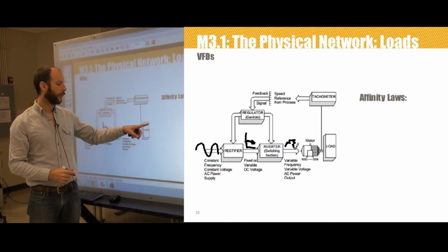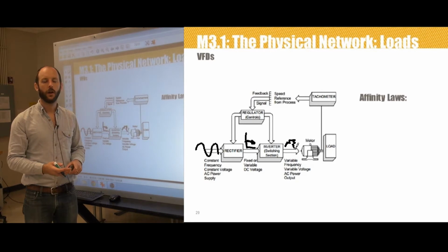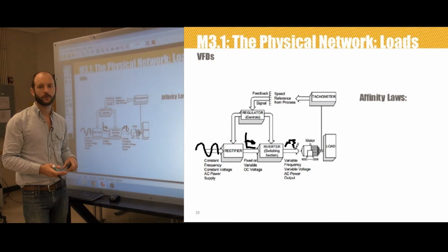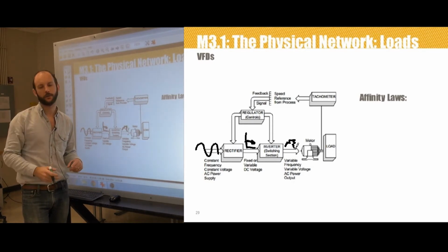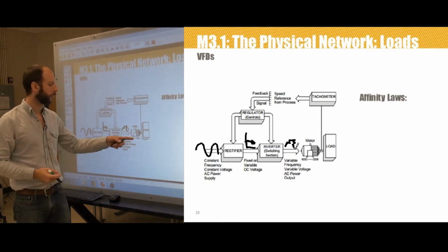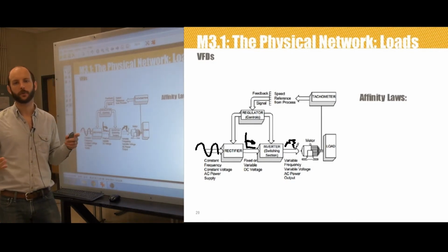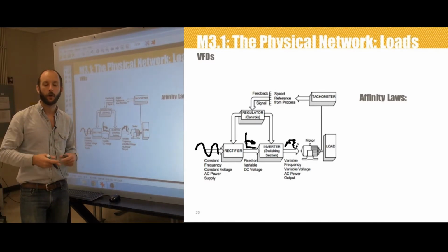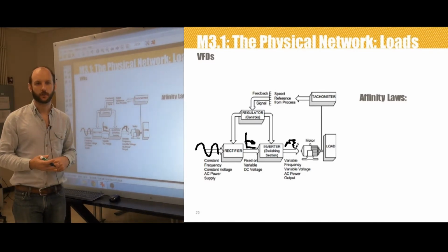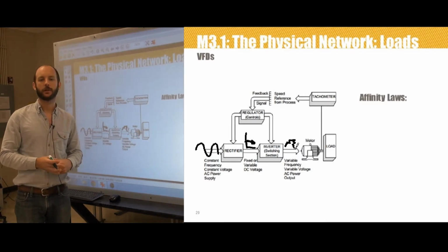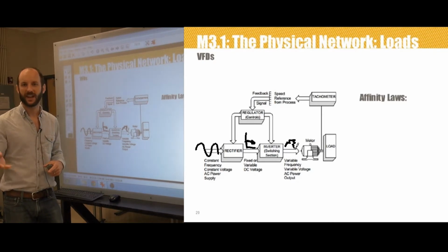Why is this done? Well, in many systems, this load is non-constant. For example, a pump used in an irrigation system is often used to deliver different flow rates based on the time of day. Traditionally, different throttling devices such as dampers, valves, and different bypass systems have been used to reduce the flow rates. So I've mechanically changed the load by using some sort of throttling device. Although that method is effective, such devices are really not energy efficient whatsoever, right? You're using full power on the load and you're using a mechanical device basically to waste that energy.